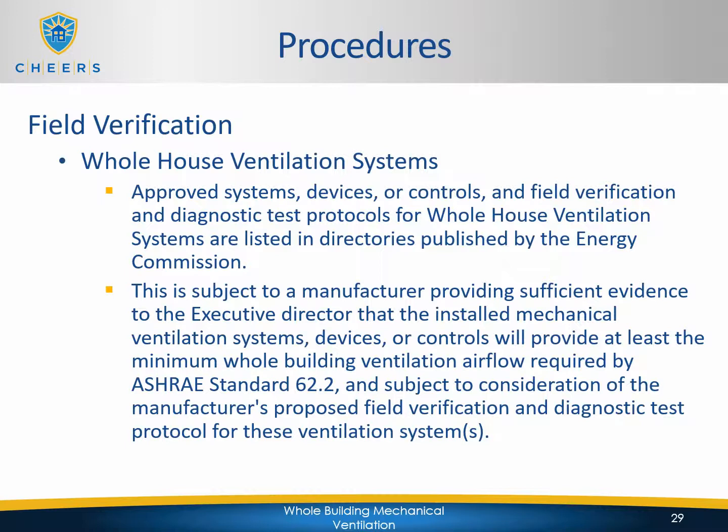To be listed in that directory, the manufacturer must provide sufficient evidence to the executive director of the CEC that the installed mechanical ventilation systems, devices, or controls will provide at least the minimum whole building ventilation airflow required by ASHRAE Standard 62.2, and subject to consideration of the manufacturer's proposed field verification and diagnostic test protocol for these ventilation systems. So any system that you're going to encounter out in the field does need to be approved and listed in that directory that can be found on the Energy Commission's website.